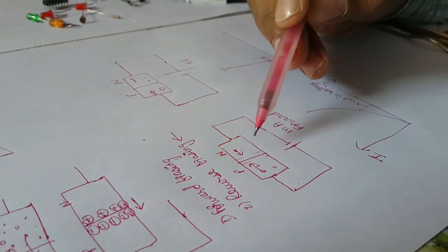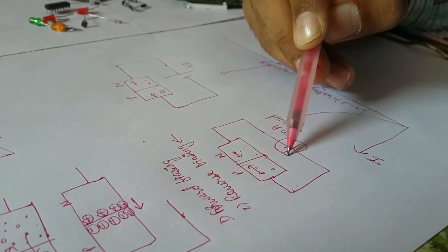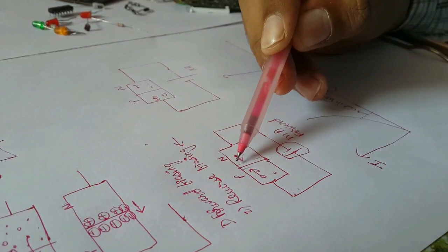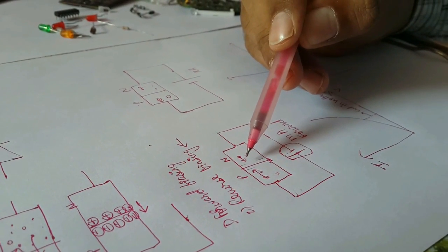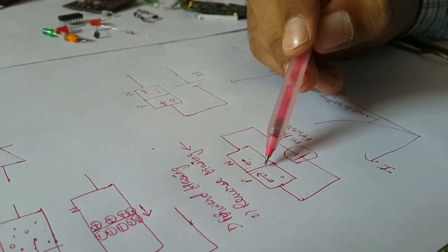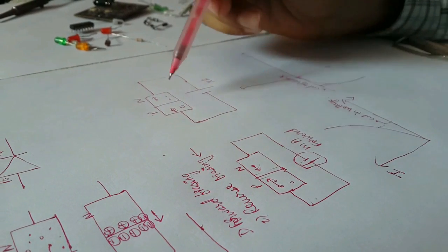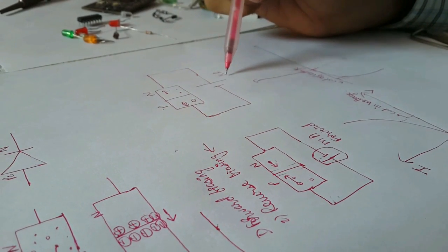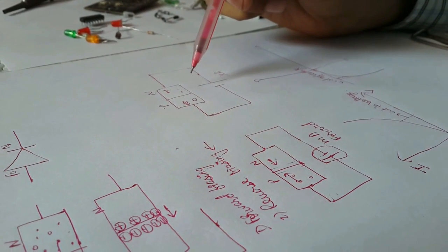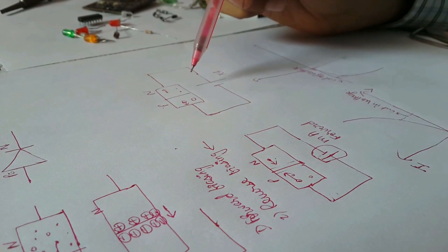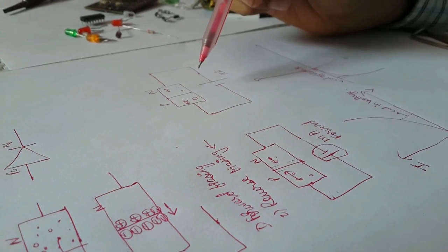Here we have seen that the potential barrier and this applied potential both are opposing each other. So we have broken off this potential, and after some time it will have very little, the junction will become very thin, and so the majority carriers can easily flow and the current will rise, whereas if the applied potential is in the same direction as the barrier potential, it becomes thicker and thicker, and the flow of majority carriers is not possible. So this is, for our Physics for Smart Brains, the working of the diode.